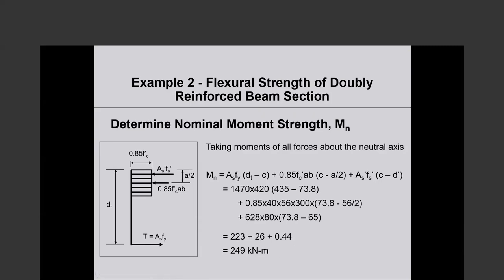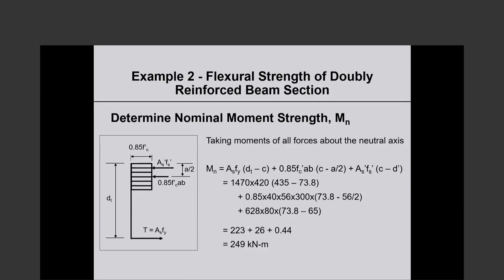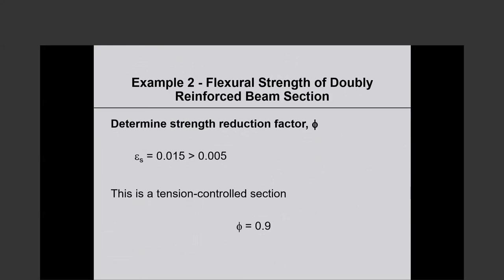If you have compression reinforcement, it does not typically contribute a whole lot to moment strength, and things are a lot simpler if we simply neglect the compression reinforcement. I'm not telling you to neglect it. All I'm telling you is that many designers simply forget about that. They just disregard it, and there is no detriment that I'm aware of. It doesn't make much of a difference, but theoretically, definitely you should consider it.